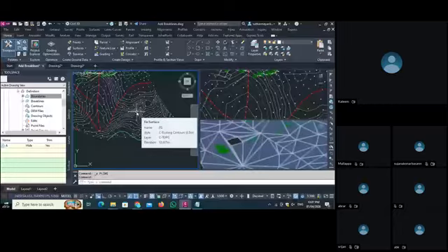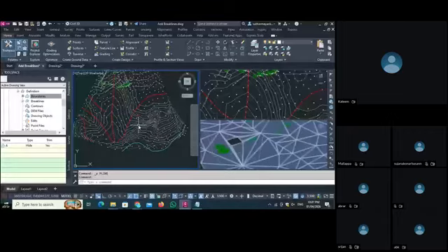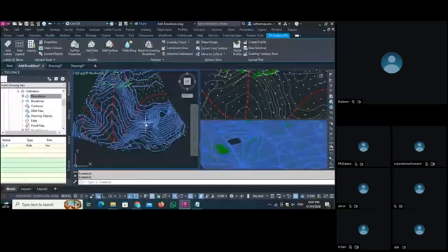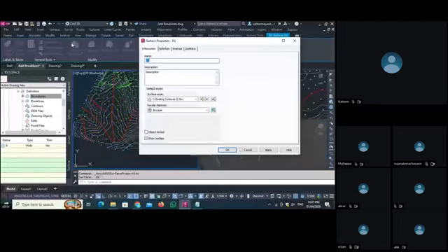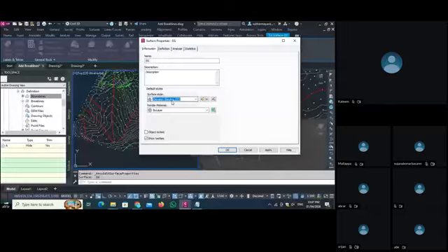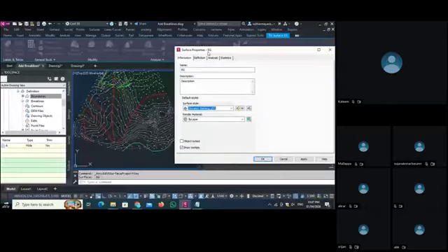All right, okay. So that's why it is important to understand with this only. So what happened? For surface analysis, what we have to do? We select the surface. As we select the surface, we show the surface properties here. In surface properties, we have to set the style. First of all, we set the elevation banding 2D style.